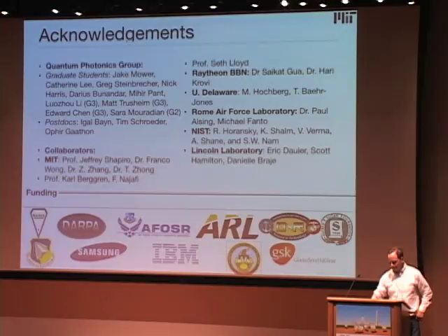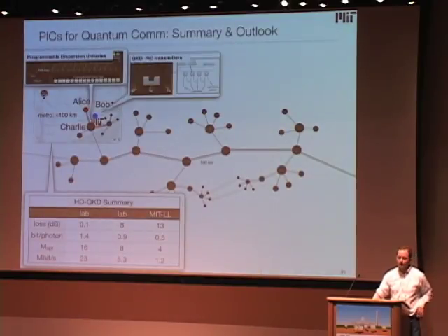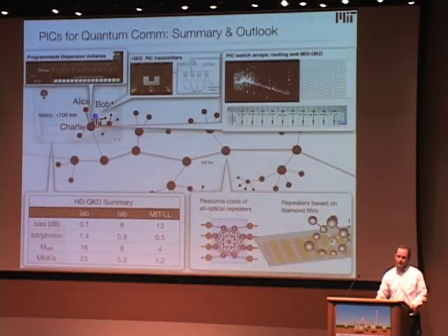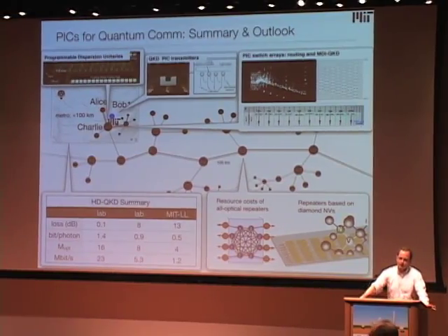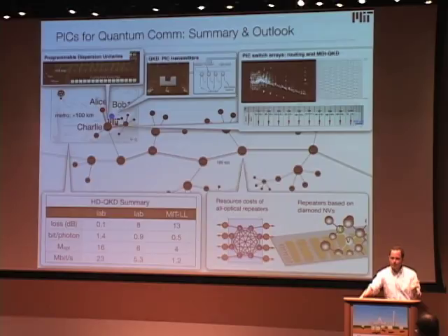Thanks. What is your switching speed of your switches, and what is the limitation? Yeah, so we have two kinds of modulators for switches. The first type uses free carrier dispersion. And basically, there, the refractive index change is achieved by either injecting or depleting some electron gas into the modulator. When you do that, there's no way of getting around also absorbing some light with this electron gas. And these modulators have some fraction of a dB per modulator loss, but they can go at tens of gigahertz.